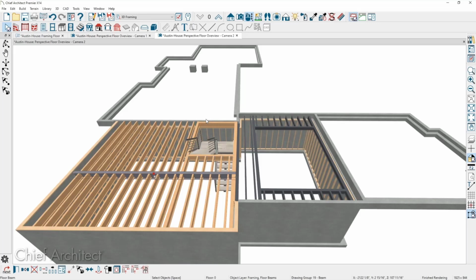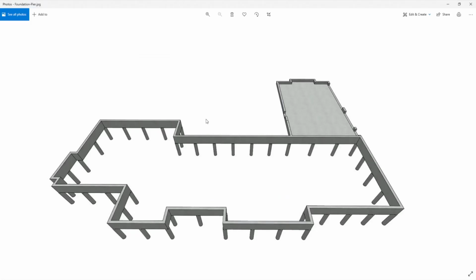So that'd be an option too. Okay, but there's no option in a pier. Yeah, once you've drawn a pier, we don't have a bell option for that. Gotcha. And then if you've got an elevated crawl space instead of a subterranean crawl space, how do you get it to elevate? I'm sure it's just a dimension somewhere. Sure, you can click in your room and you can change the room height.